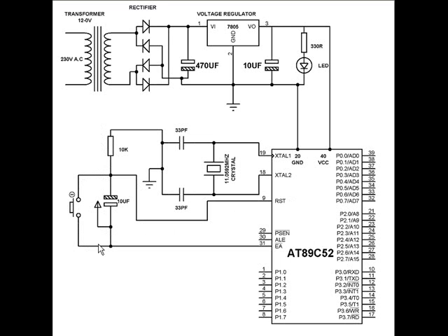We have connected a button switch, a push to on switch. That means when I push, it will be on, when I release, it will be off. And this push to on switch at any time will discharge this capacitor, because if I press, this capacitor will be discharged. When I release this, again the capacitor will start charging, and this point goes high, and then after the charging is over, this point goes low. So the program again starts from the beginning. Every time I press the reset button, the program starts from the beginning. So that is the purpose of using these standard connections of the microcontroller.